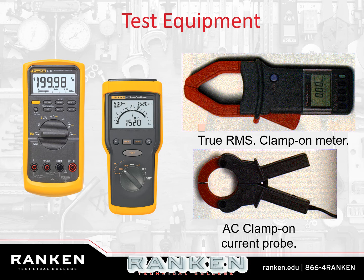If you were getting an overcurrent alarm or too high of current or an overload alarm, you need to see and measure the current. If the current doesn't exceed what the overload is set at, but you're still getting an overload alarm, well, then you have a problem with the sensing equipment in the drive. It's not overloading, it just thinks it is. And that can happen. So you need to be able to check the current. Remember, we do not check current in series with AC lines. We use a clamp on.